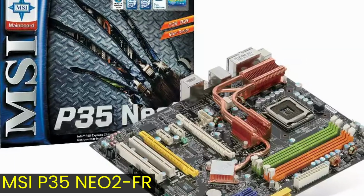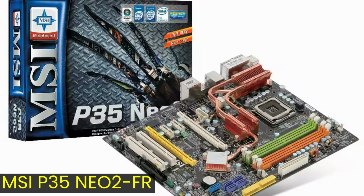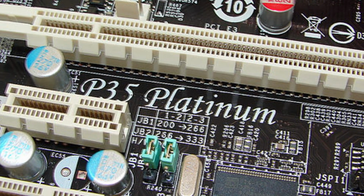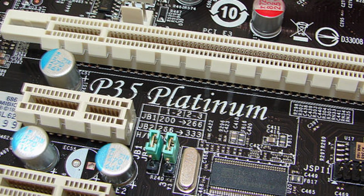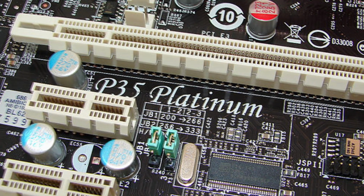Browsing through the manual of the MSI P35 Neo 2-FR motherboard, we find on page 2-19 a feature called Hardware Overclock FSB Jumpers. By configuring these jumpers in different positions, you can change the front-side bus frequency between 200, 266, and 333 MHz. This in turn increases the CPU core frequency.